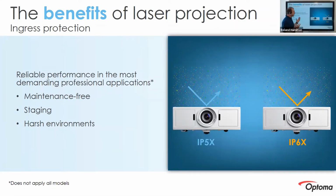We would obviously recommend keeping the projector as dust-free as possible, but at the same time, our products are relatively impervious to the outside elements within reason. IP5X could be considered dust resistant, where IP6X is dust proof. Perfect for staging or harsher environments. Like say you're going to install laser projectors in a theater and there's going to be theatrical smoke, a laser projector will stand up to that a lot better than a lamp-based projector.